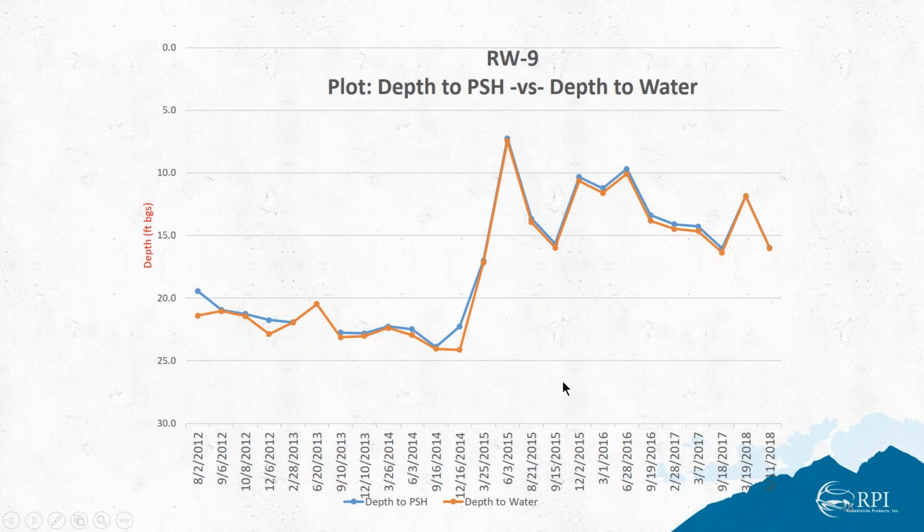The other thing that we noticed at this site was that, of course, we had benzene. So we looked at historical data. We looked at wells where free phase had been observed and where it hadn't, and compared that to the groundwater benzene value, and came up with a rough correlation that we felt we could use on the site. Once you reach a concentration of benzene between 50 and 100 ppb, it's likely that you have groundwater in contact with free phase. If it's below 50 ppb, we're in a zone where it's unlikely that we're going to see free phase at that location again.